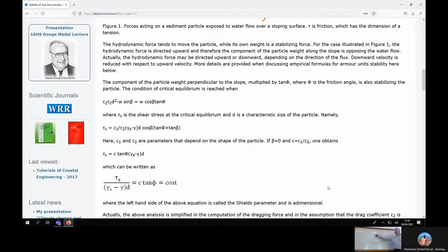We will see how we can compute the shear stress, but this implies the assumption that the shear stress can be easily computed and does not depend on the characteristics of the fluid motion, which, if you know something of basic hydraulics, is not really credible, because the shear stress caused by a laminar flow is different with respect to the shear stress caused by a turbulent flow.